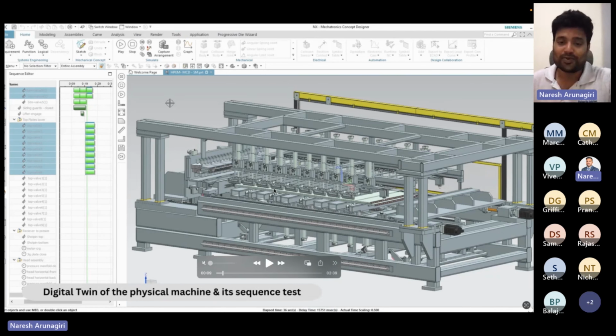Now, the second step is where the PLC comes in. So now we integrate the machine with the PLC program. That's where the functional test of the cylinder comes in. When you define the cylinder, it has to work in multiple ways. When it's turned on, it has to move up, and when it's turned off, it has to move back, right? That's how we defined it.